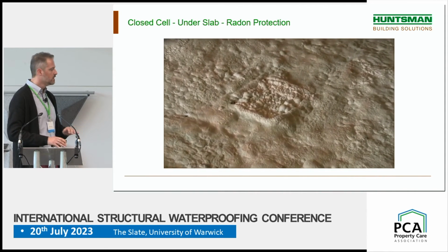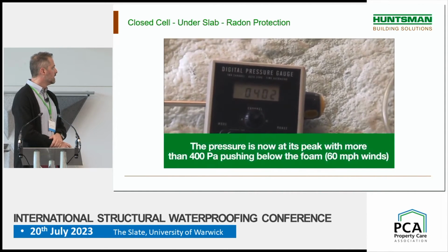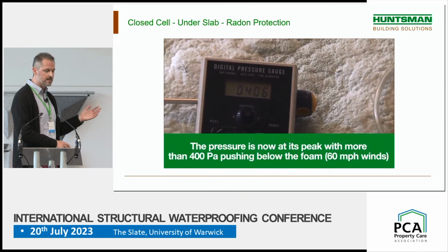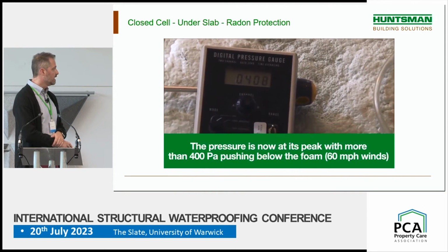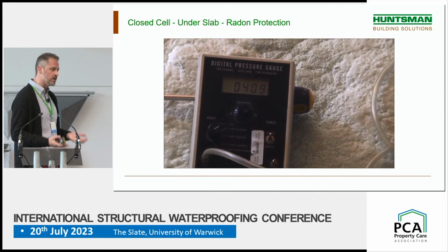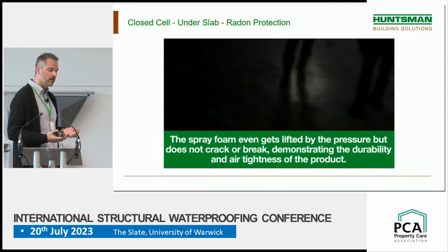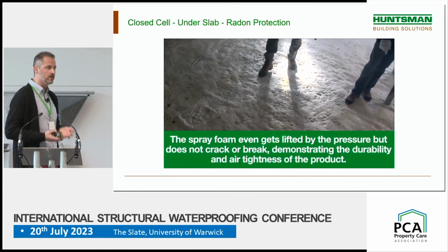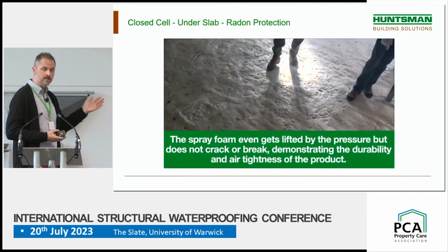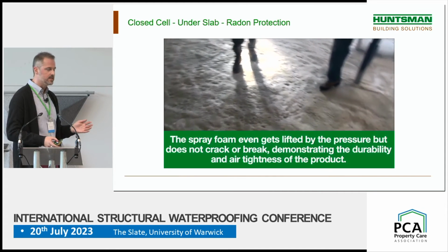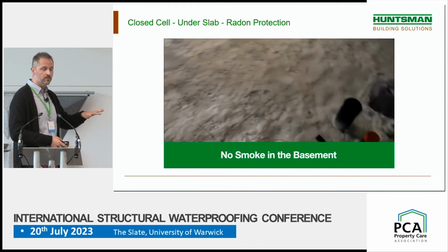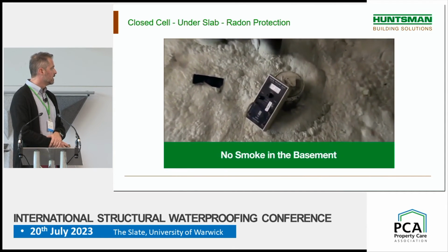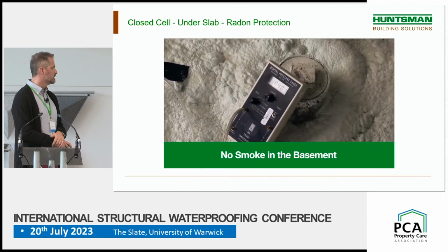There's no joints, no cracks, no hole. And you see the pressure is now at its highest, at 400 Pascal, which is really high. The pressure is pushing under the foam, and you can see what's happening. The foam gets lifted by the pressure, but still it's not cracking, it's resisting well. And with the weight of the concrete after, it's going to be even better. So you can see 400 Pascal still.